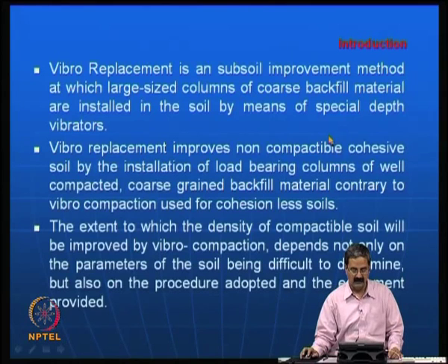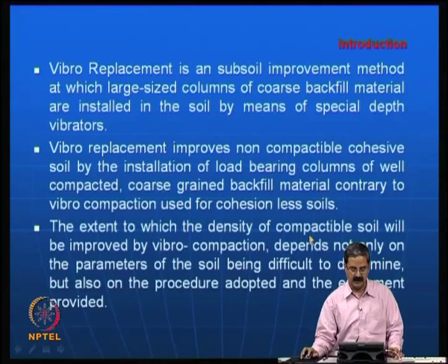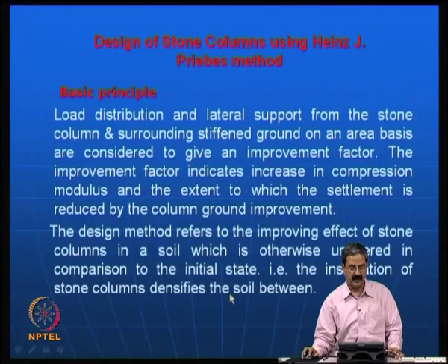But then we have what is called the elastic method also, which is very interesting, and it has been very well used for the vibro replacement method using stone columns. The very important thing that one should understand is that the extent to which the density or the properties are improved depends on the parameters of the soil, and most of the soils are difficult to measure. In fact, they are somewhat complicated.